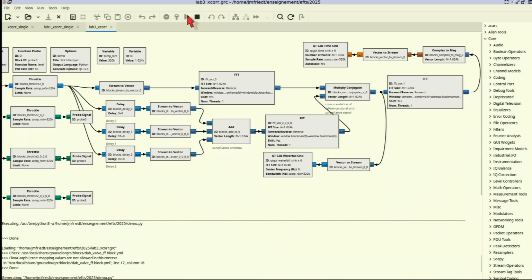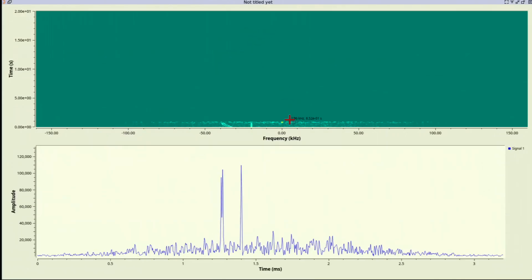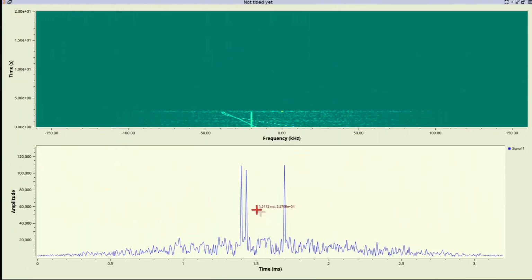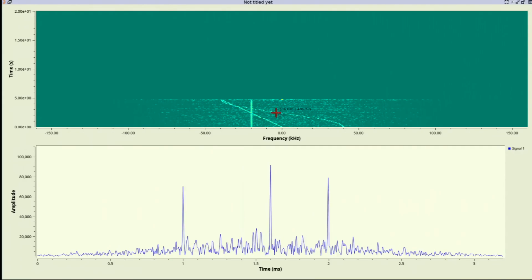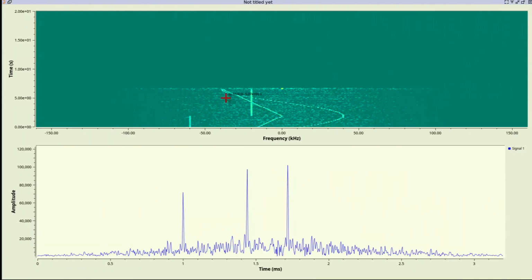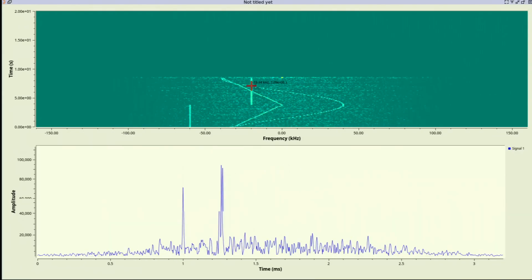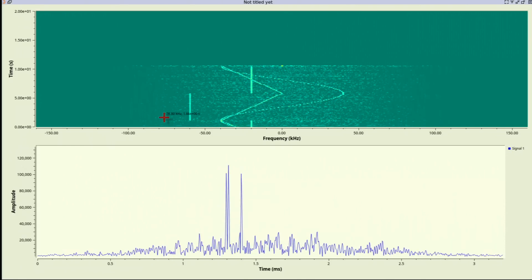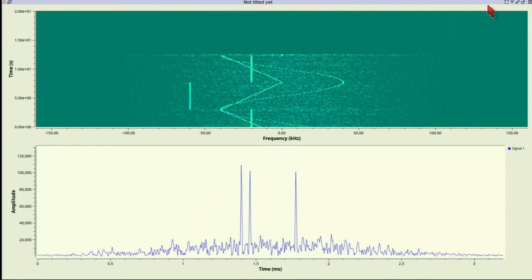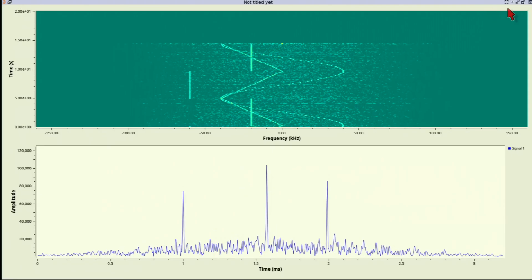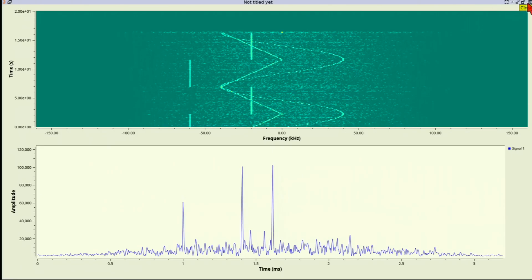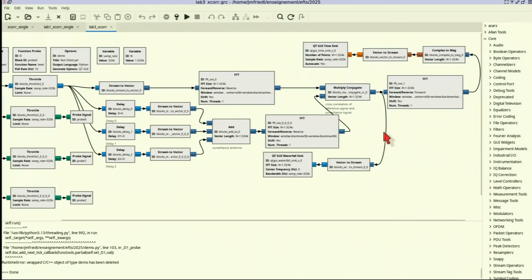And when you run this, what you will see is the 3 targets with 1 target delay shaped as a sine wave, 1 target delay shaped as a triangular wave, and 1 target shaped as a square wave. Okay? So you see that by understanding the correlation, the Fourier transform analysis for computing the correlation, and by understanding the linearity of the Fourier transform, you can actually implement your radar using GNU Radio, despite GNU Radio not being fitted with a correlation function.